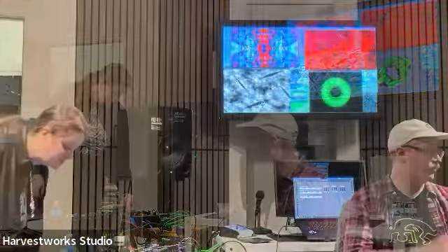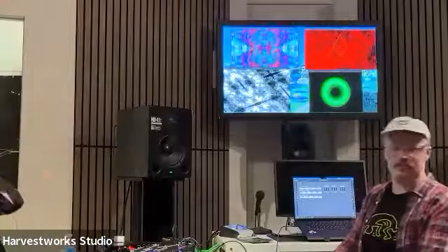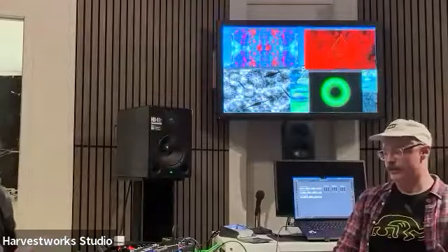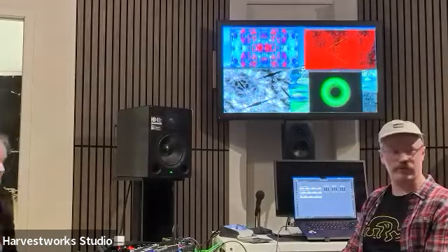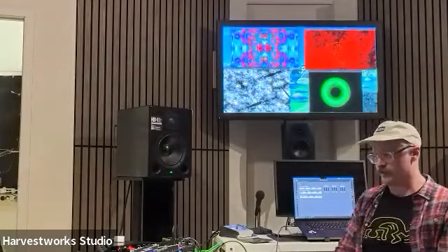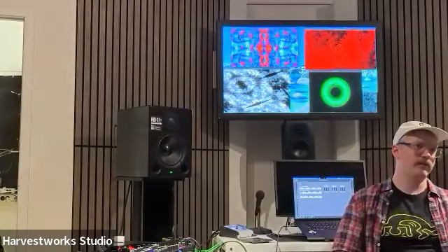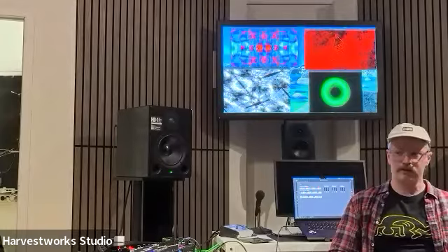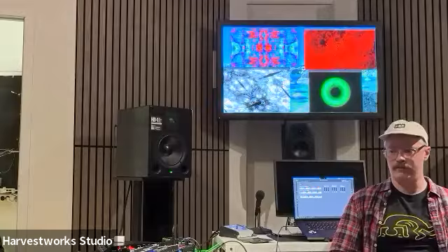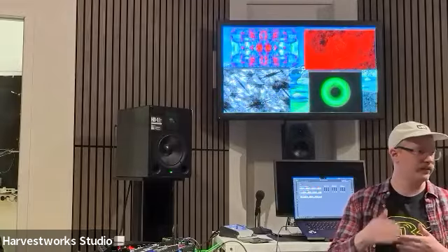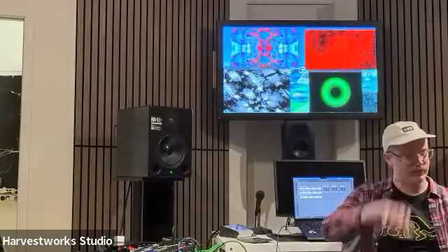So before we got into the introduction, I was alluding to how the CV and MIDI outputs work. The CV is 0 to 5 volts, and the MIDI has 6 channels of output. The first three are note data. It's the same note data coming at different speeds, with a certain number of notes per second following the amplitude.